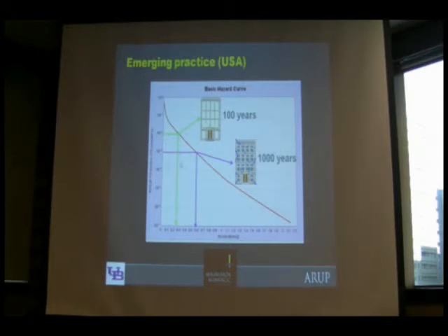And then as we increase the return period on the earthquake shaking, we move from, say, frequent shaking to very rare earthquake shaking, perhaps shaking with a return period of about 1,000 years, where we might accept damage that's associated with the performance level of collapse prevention. But we're now marrying performance and hazard, and we put the two together to form a performance objective.